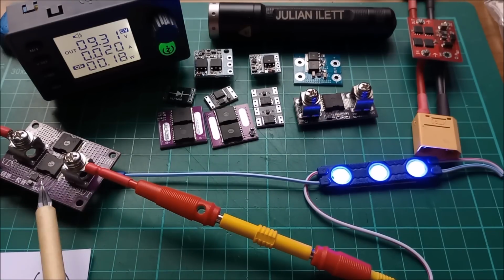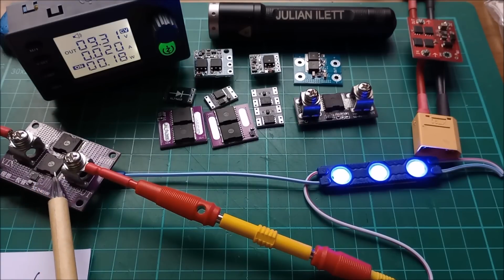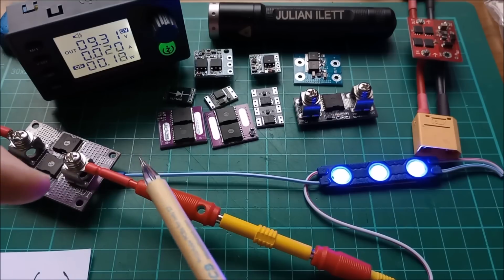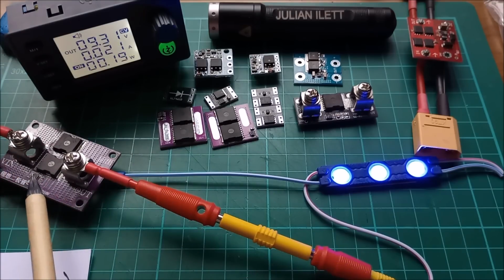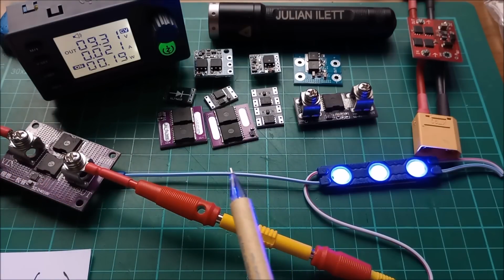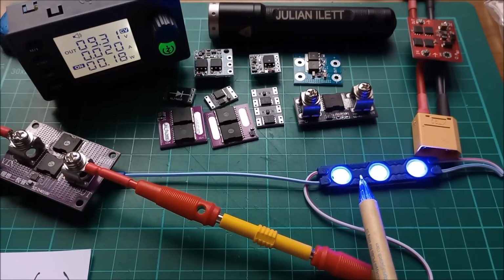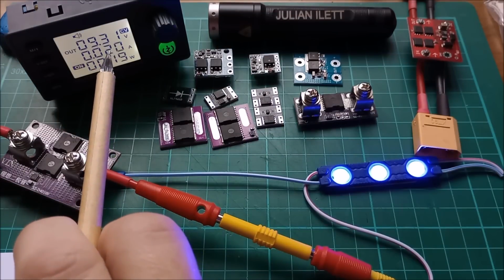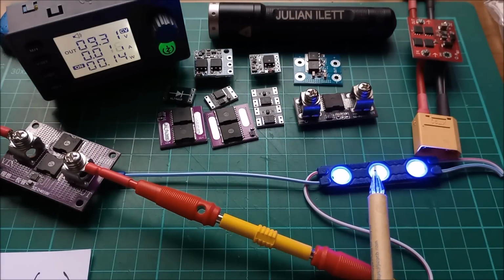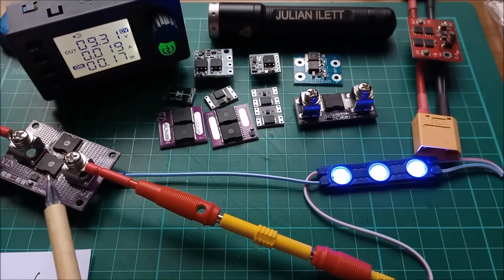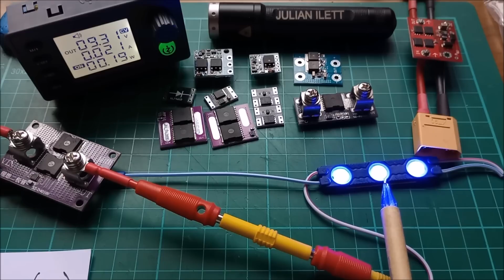If a significant amount of current is running through the body diode, then you will get this 0.6 volts of difference. That enables the chip to operate and charge up this capacitor. The on time is something like 2.5 seconds, and the off time is something like 50 milliseconds. This is only 20 milliamps. If I put more current through this controller chip, then you probably won't see this pulsing at all. In fact, you didn't see this pulsing.